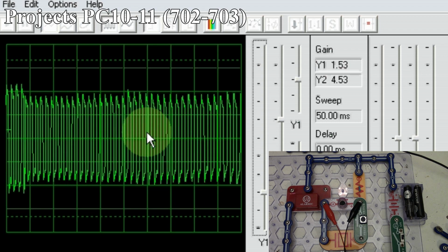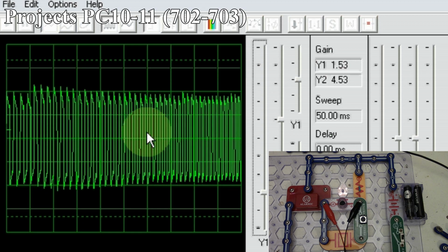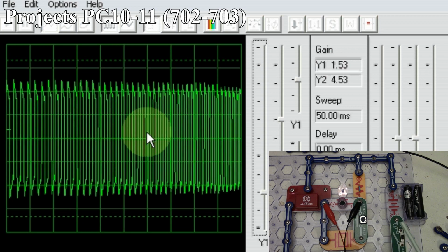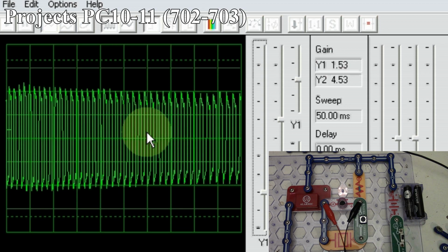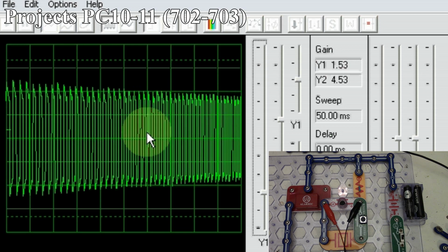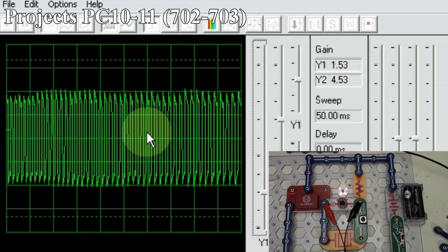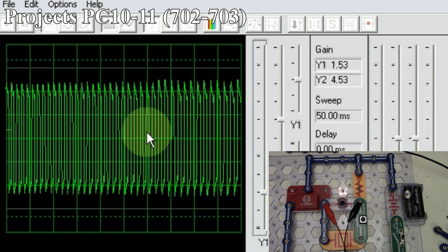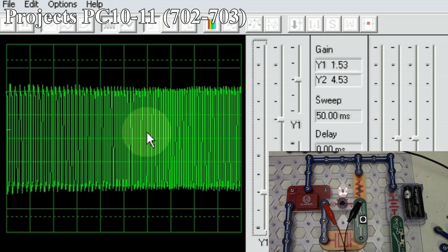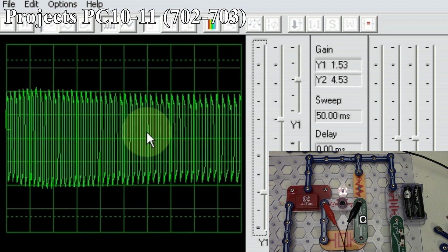And so this is how AM radio stations work when you're listening to AM radio. They have a controlling signal, which is the frequency of the station you're listening to, say 1000 AM, which is 1000 kilohertz. And then they have all their audio, like their voice or music or whatever they're doing on the radio station, superimposed on top of that signal, and then it's sent out over the airwaves, and then you receive it on your radio. So that's how it's demonstrating AM, or amplitude modulation.